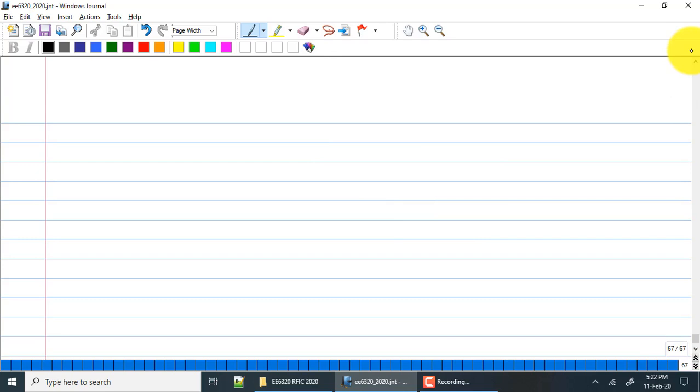So let us go back to the common source LNA. We discarded it because you couldn't match the input to 50 ohms because the input was capacitive. But it turns out that if you take a common source transistor, for RF designs, you can't neglect the gate source capacitance.